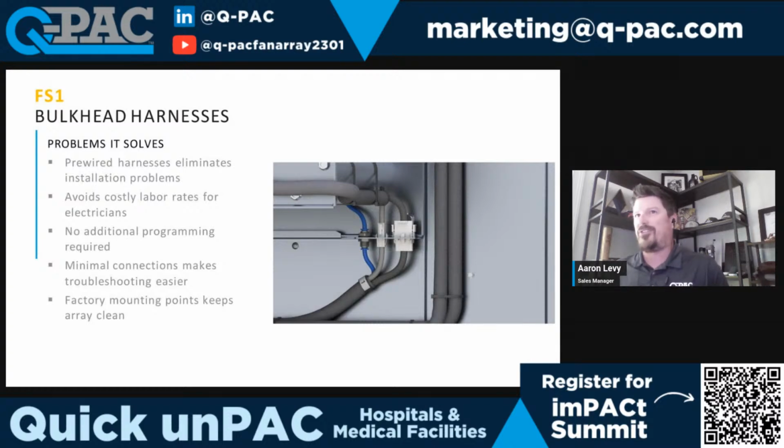The problem is that to do 575 would need a whole new set of electronics. The way the current electronics are built for each particular model, that cabinet height is only so big, and the capacitors needed for 575 voltage and all the other components needed to handle that voltage won't fit inside that chassis.